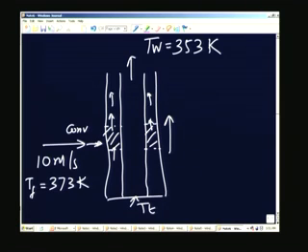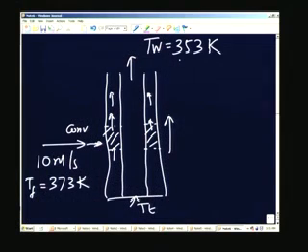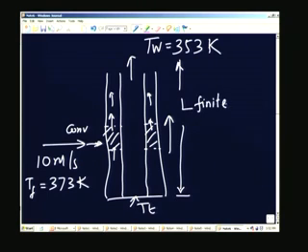The model is exactly similar to what we had earlier in the case of the lead wire model. There is no difference really. The only difference between the lead wire model which we had earlier and this case is that the lead wire was of infinite length or very large length. Therefore, we had a simple solution to the problem. Here we have a finite length for the immersed well. This L is given from the wall to the depth here. This length is a finite quantity, finite length.